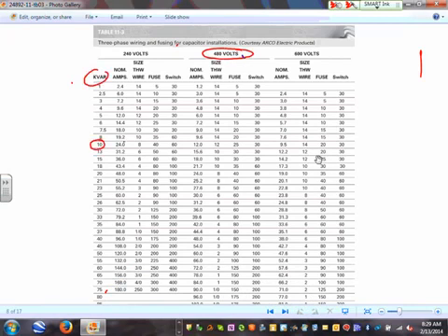Can you guys see that? The full load amp of this baby is this. Normal full load amp at which voltage? The normal full load amp, guys, for the 480 is right here, 12 amps. The conductor size is number 12. The fuse size is 25. The disconnect is 30. So they did the calculation for you.